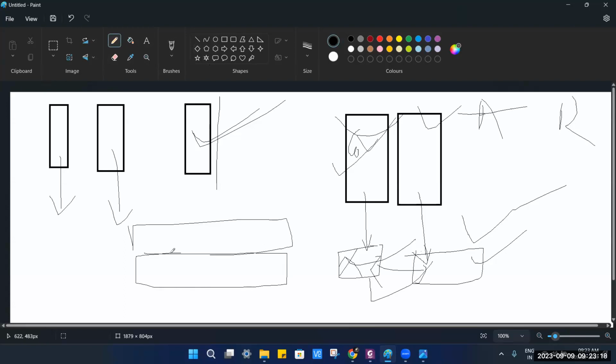So CAN, basically, CAN is there, or something else will be there. Depends on what is the legacy interface protocol. Correct. Legacy protocol. Yeah. So mostly in automotive they will be using CAN, because mostly all the ECUs, electronic control units, which are there in the automotive, they will be doing the communication with the CAN. So yes, the lower level driver should be CAN, or some companies use LIN as well. Yeah, heard of them too. Yes. So it depends which communication protocol they are using to communicate with the ECUs. If they are using CAN, yes, the low level driver should be CAN. If they are using LIN, the low level driver should be LIN.